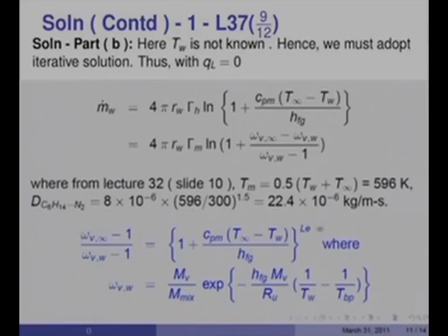Of course, in each case you must calculate gamma m and gamma h for each temperature, because the mean temperature would change for each choice of TW, and T infinity is 850 as you know already. So, one needs to iterate on these two equations.